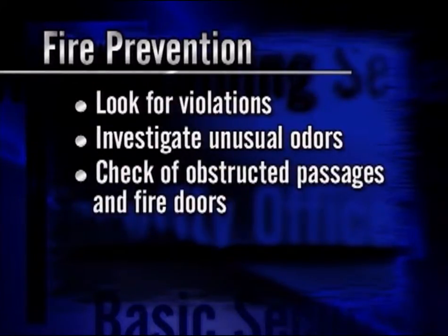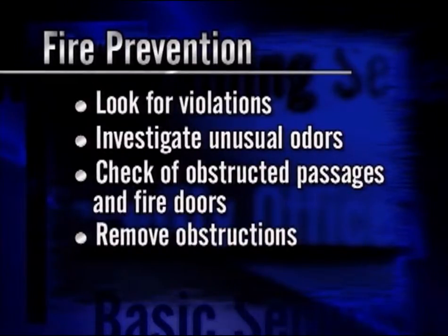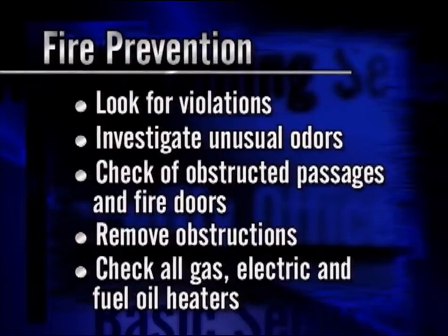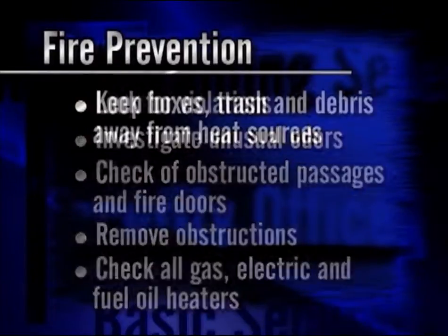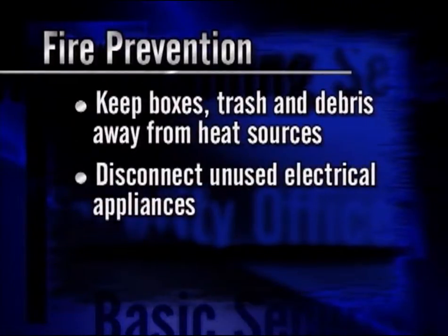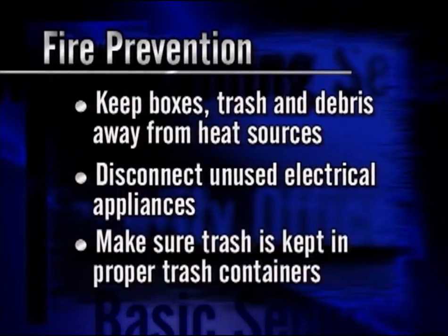Check for obstructed passages and fire doors. Remove obstructions from in front of fire alarms, hydrants, and alarm boxes. Check all gas, electric, and fuel oil heaters to make sure they're functioning properly and not overheating. Keep boxes, trash, and other debris away from heat sources. Disconnect unused electrical appliances. Make sure trash is being kept in proper trash containers.